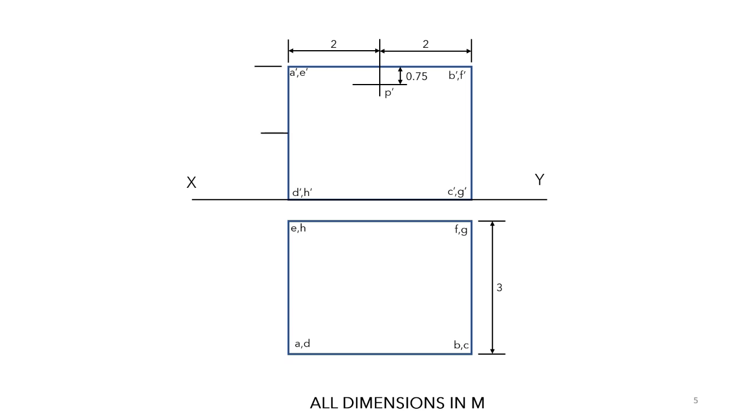Now we have to mark the location of the switch from the front view. The switch will be located at the center line from the front view, so it will be at a distance 1.5 from top and bottom, and we name it small q dash and we join them.